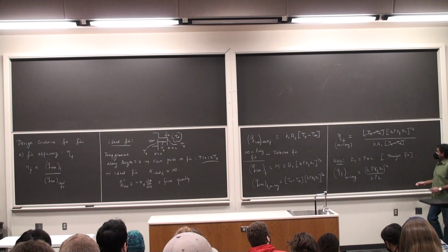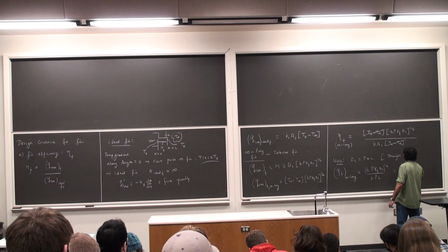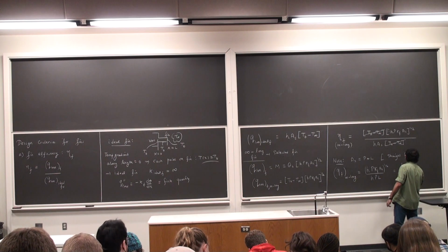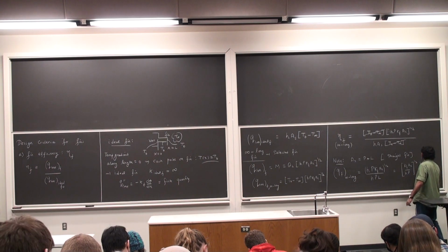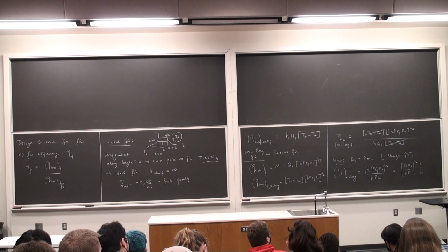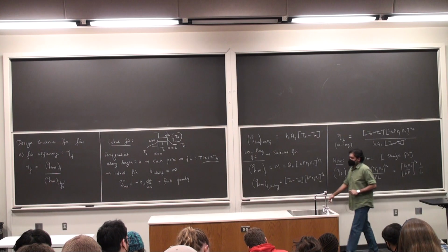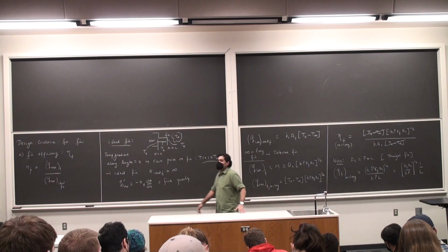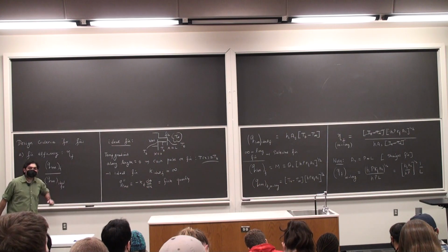So if I cancel off some of these terms, I end up getting Kf Ac over h P to the power 1 by 2 times 1 by L. Can anybody tell me what those terms in the brackets with the square root 1 by 2 represent?